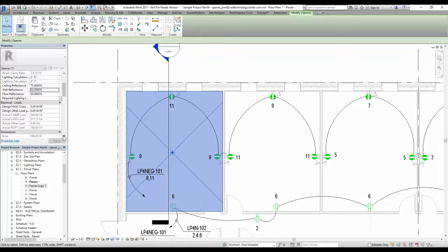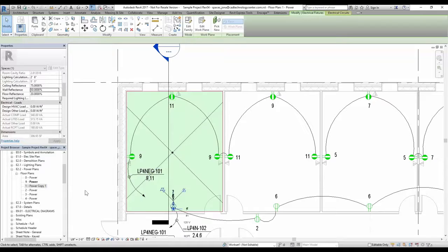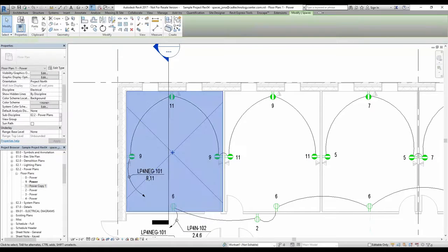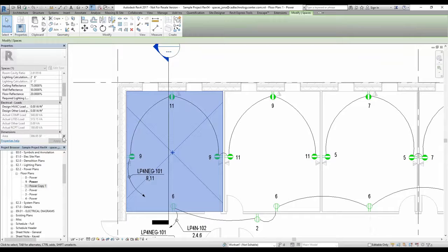Now further down, under our electrical loads, we have all of our different parameters based upon the load classification. So we have computer load for these 3 receptacles popping up at 540 VA. We have some lights that are showing up in the space. And we also have one receptacle down here in the bottom, giving us 180 VA.